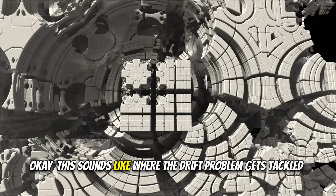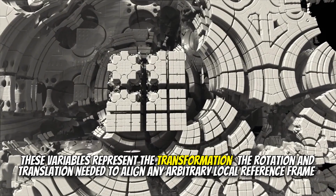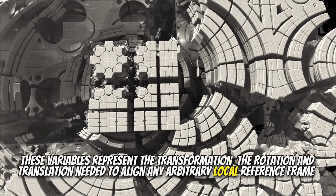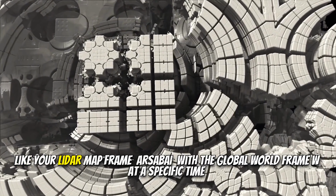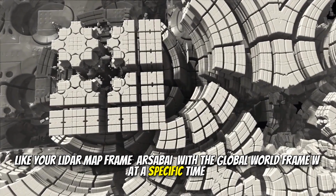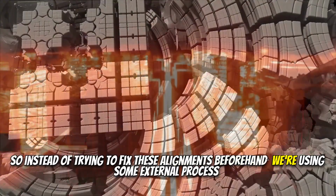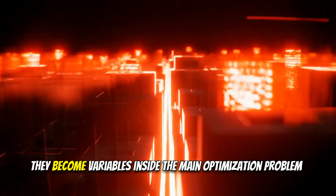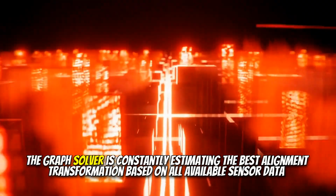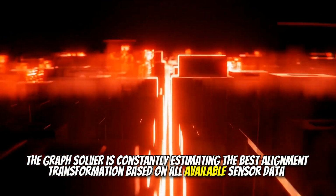Okay, this sounds like where the drift problem gets tackled. This is it. These variables represent the transformation, the rotation and translation needed to align any arbitrary local reference frame, like your LiDAR map frame, R sub I, with the global world frame, W, at a specific time, K. So instead of trying to fix these alignments beforehand or using some external process, they become variables inside the main optimization problem. The graph solver is constantly estimating the best alignment transformation based on all available sensor data.